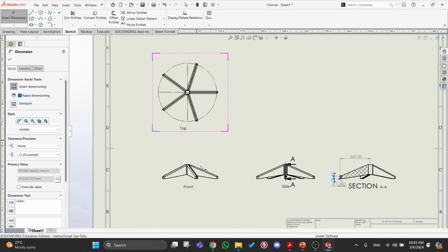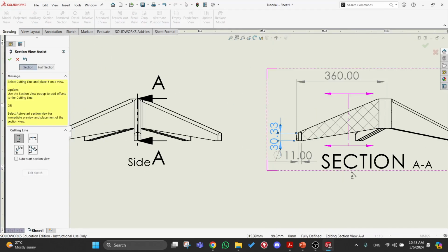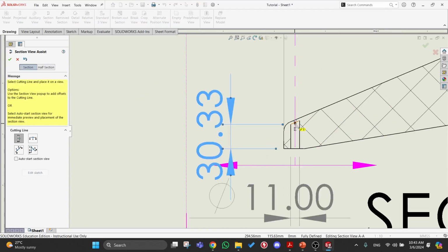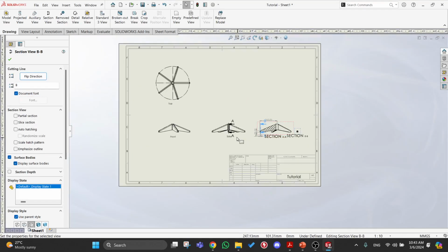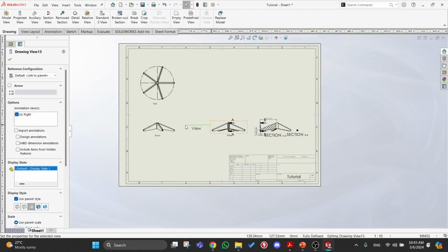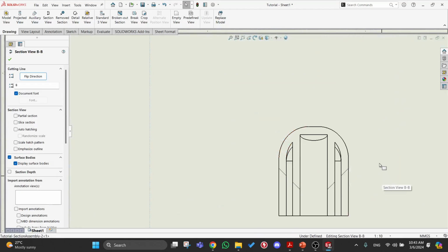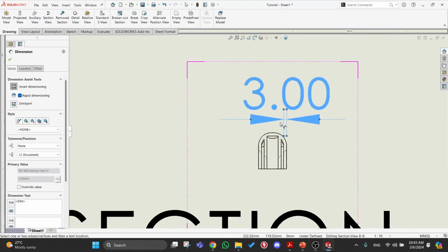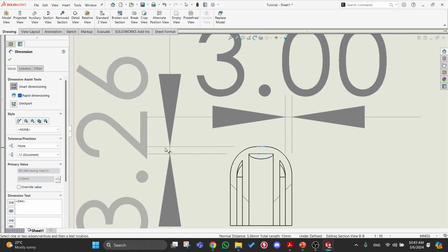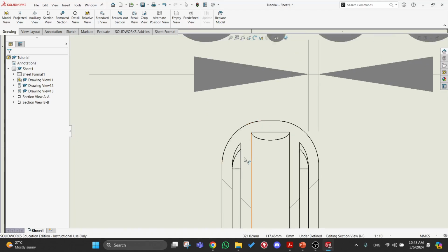How do you check our wall thickness? You can slice this part, right? You want to slice down here in the middle. That's one of it, right? So that you have this part, your section BB, and then using this you can check your height. So this is 3, this 3, this 3 point something. Not very uniform wall thickness here, but yeah, it is what it is.